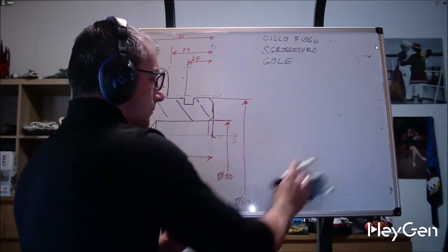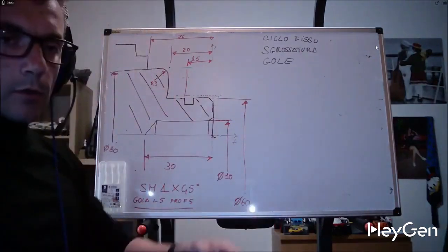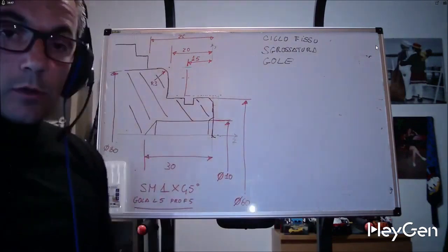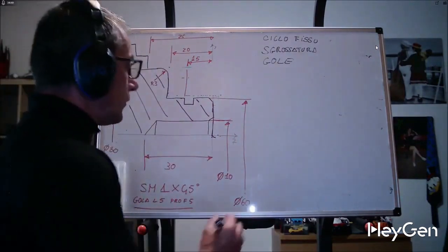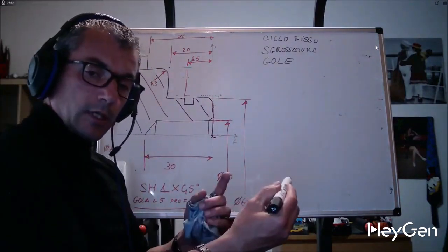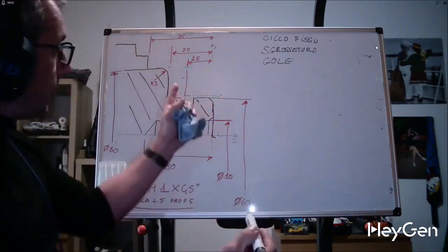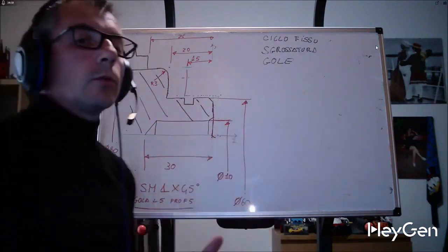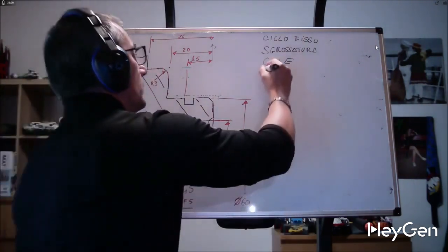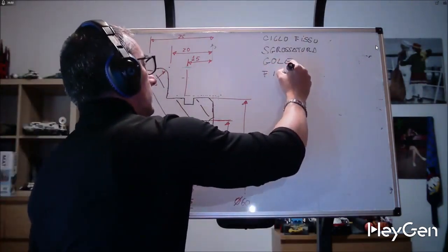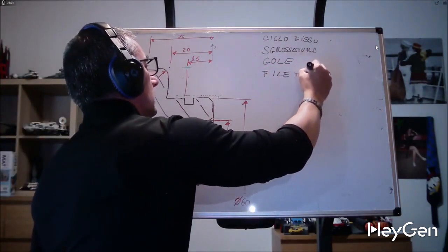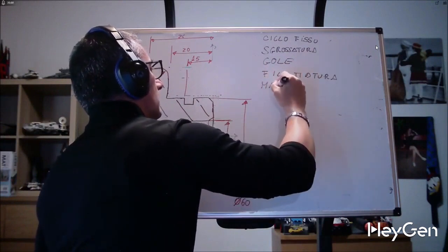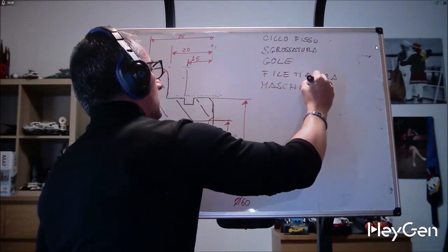What about that? However, if you have a front or wide groove of 30mm to make with a tool of size 4, 5 or 6, a fixed cycle will definitely be useful. Once you have determined the width, depth and position of the groove, it will clear it for you, breaking the chips, with a fixed cycle for threading, tapping and drilling.